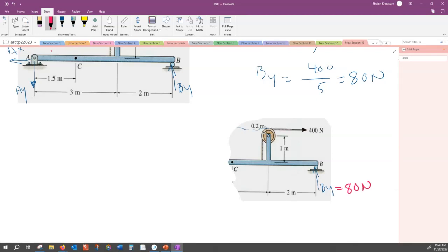And at C, this is a beam. How many internal forces develop at C? 3. And what are the positive assumptions? The positive assumption for N is like so, N of C. And the positive, because it is the right-hand side free body diagram, the positive V is pointing up, V of C, and the positive bending moment looks like that, M of C, correct? All right, is this free body diagram solvable? How many unknowns? 3 unknowns, 3 equations.